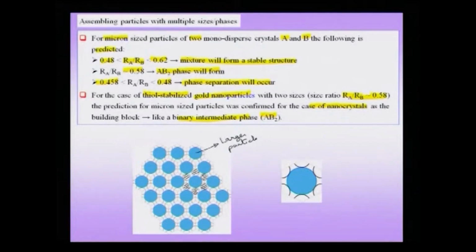Now, therefore, I can actually draw a unit cell for this structure, which is now a 2-dimensional crystal with a stoichiometry AB2. This is my unit cell. But to calculate the stoichiometry to be AB2, it is better that I consider a hexagonal kind of a cell, which is shown on the right hand side here.